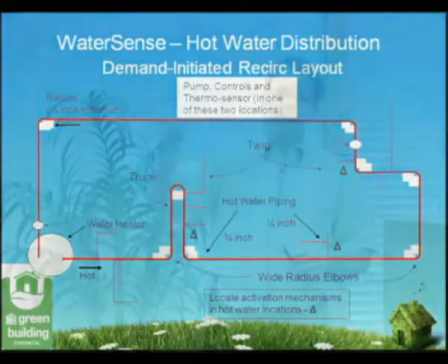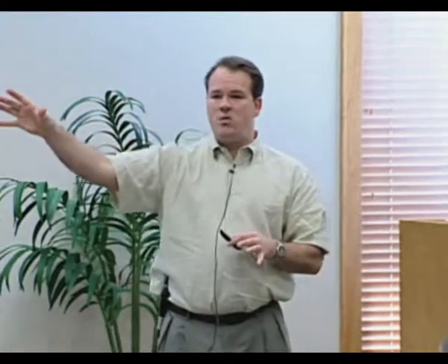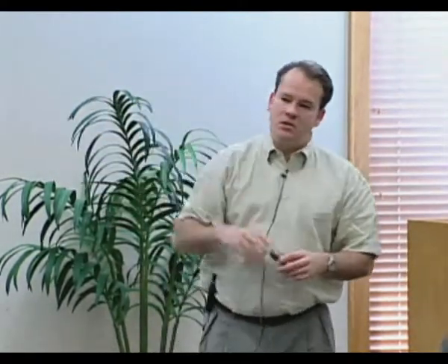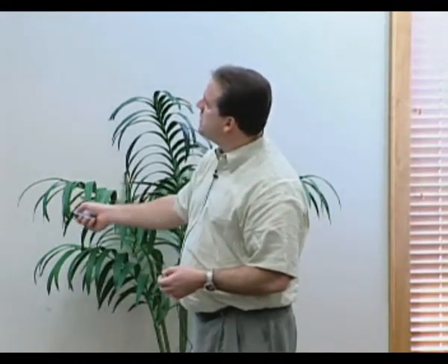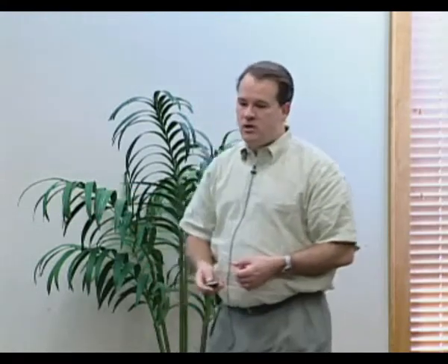So we're minimizing the amount of stagnant water sitting in a pipe. We are recirculating water through this pipe, and each one of the fixtures in the house has a little on-demand button that you push, and this little pump up in these corners begins the circulation process of the water through the home. And it is shown to reduce the amount of heated water required in the home.